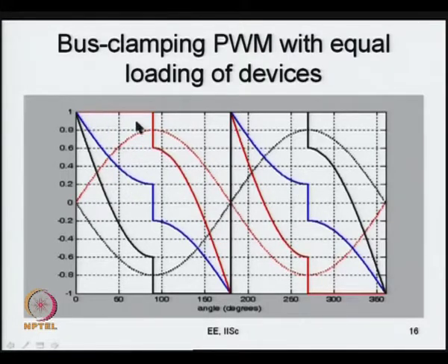In this region the devices are switching, and on account of both switching and conduction there is some power dissipated. This results in an increase in the junction temperature, but there is a delay. The moment there is power dissipation, your junction temperature does not increase immediately, and that is what is called the thermal time constant. There are various time constants involved there.